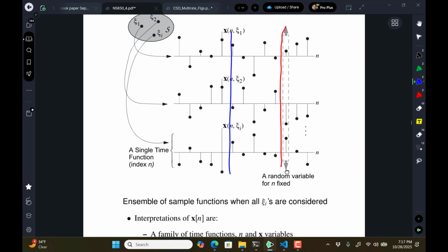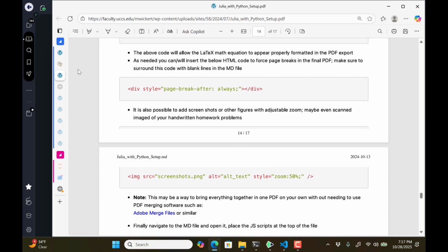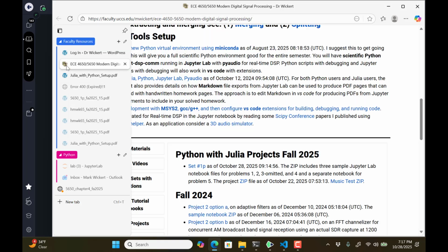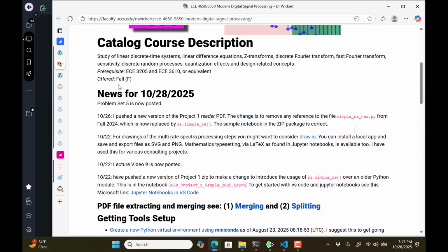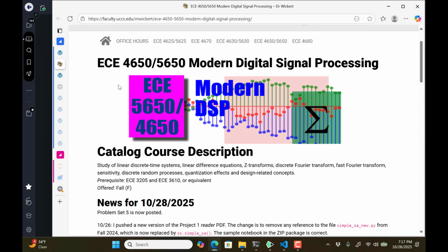There, I created an ensemble of 3 discrete sequences, and this was uniform noise stepping along in time with an equal distribution, but then it was charging up a filter. So behind this graphic is a filter that's discharged, like a capacitor that's discharged, but it's discrete time, with impulse response a^n u[n], which we saw at the very beginning. The randomness of the waveform going through the filter produces a different sample function for each experiment.